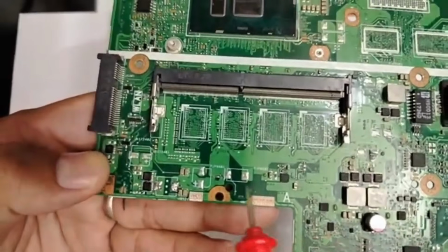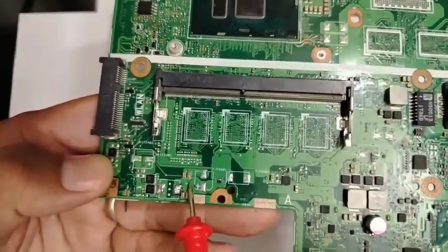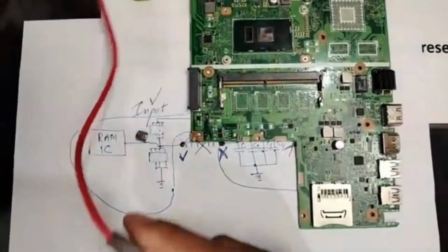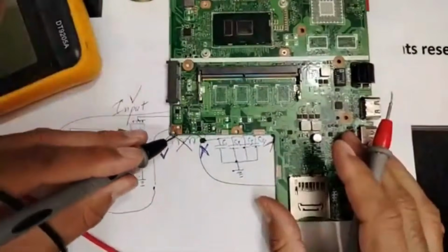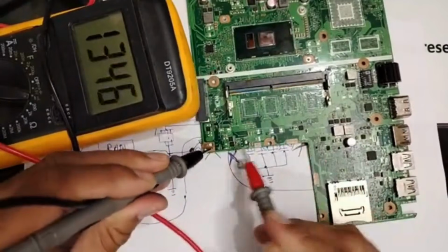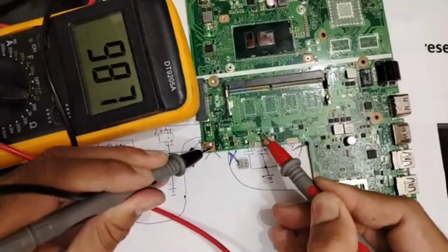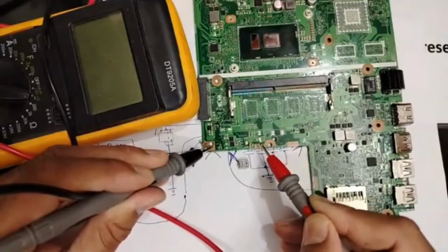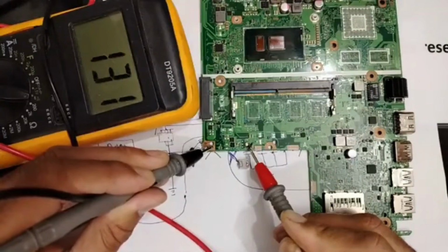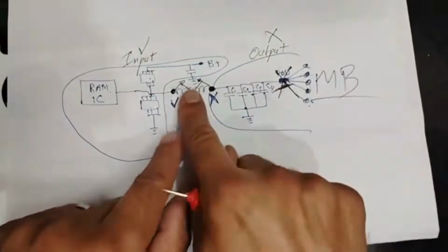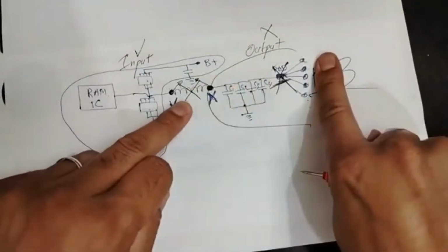Okay, I will remove this one and check this capacitor. Remember, the capacitors here are shorted. For the last time, my friends, sorry, because for me, repetition is the most important gift we have. Here, no short. When we remove this one, the short is gone. But here we have the short, still short. All these are shorted. Let's remove this one and find out if the short will disappear here or not. For now, I remove just the inductor, the coil, and I separate.